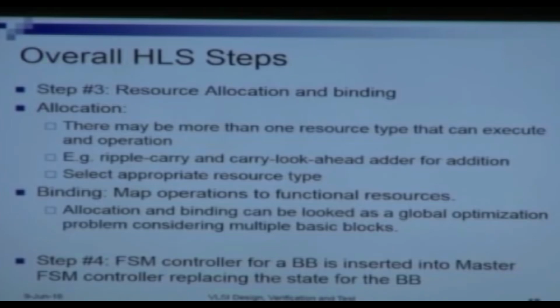Finally, the last step of high level synthesis is to build the master controller, a FSM controller for a basic block. Because I have attached timing to each of the scheduling steps, I can generate a controller that appropriately activates the functional units and, through the appropriate select inputs, the correct registers and functional unit at a given time.